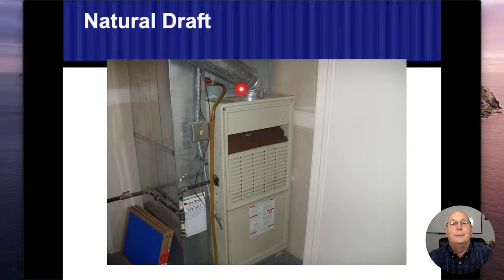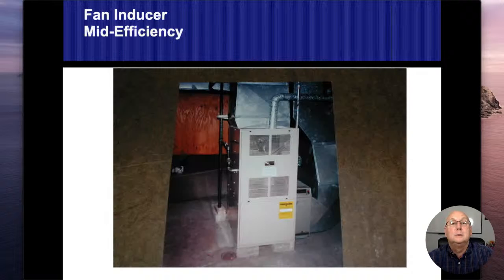This one here, I got a flexible drain. I do believe that's less than 6 inches away. And even if there is no burning, scorching, or anything on there, I'm going to go ahead and start calling that one out too. Another natural draft furnace. So now we have an inducer fan.